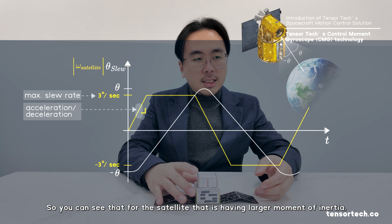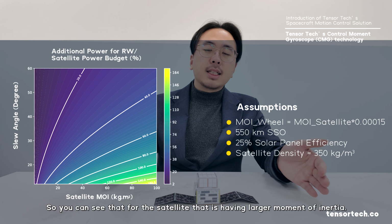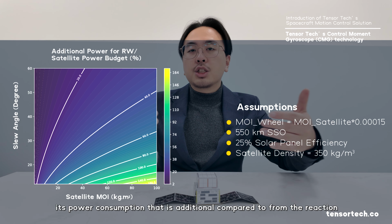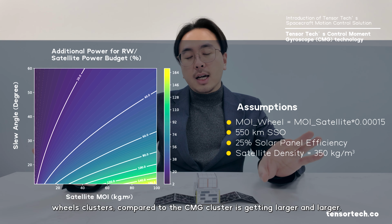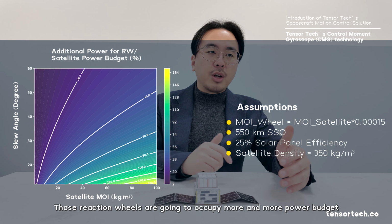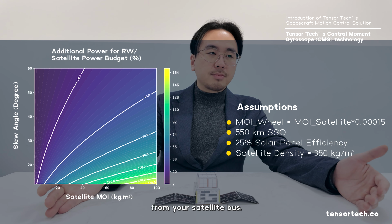You can see that for a satellite with a larger moment of inertia, the additional power consumption of the reaction wheel cluster compared to the CMG cluster gets larger and larger. Those reaction wheels are going to occupy more and more of the power budget from your satellite bus.